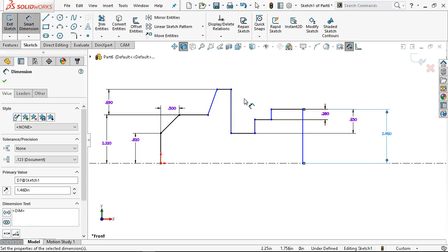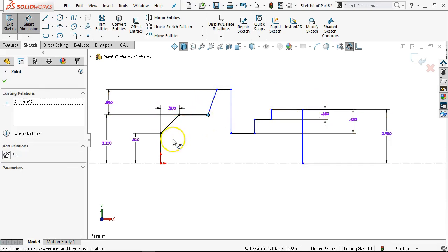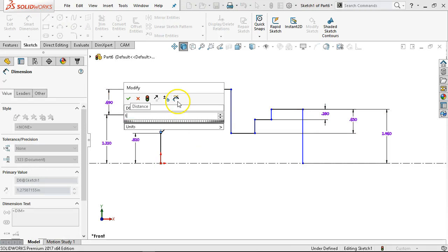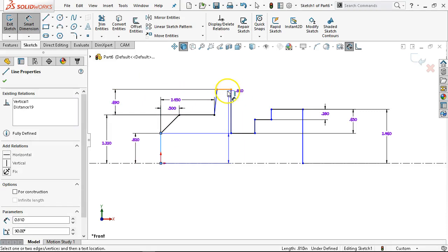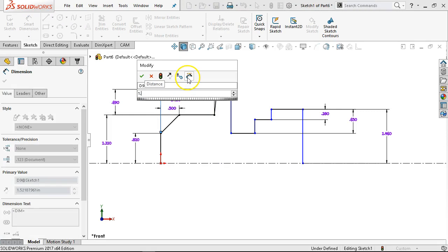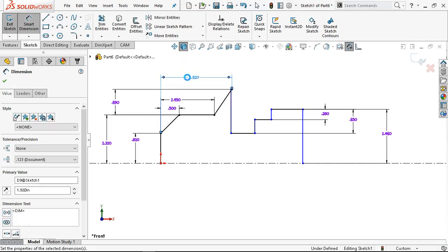All right, and there was, okay, so that was the 0.65, 0.2. All right, I think we're good that way. So we had the 0.5 and 1.45. All right, so if I do this all as baseline dimension off the datum, this is going to get kind of busy. So the alternate, when we go over to Ordinate, it's going to be in the next couple anyway. We would clean this up a little bit using Ordinate dimensions rather than having all of these stacked up.